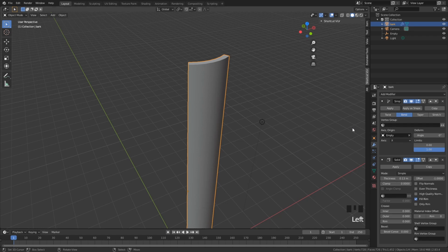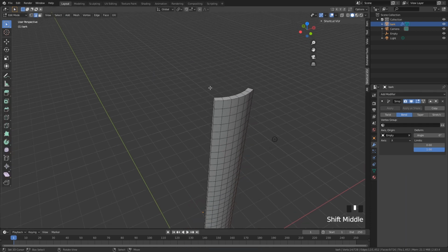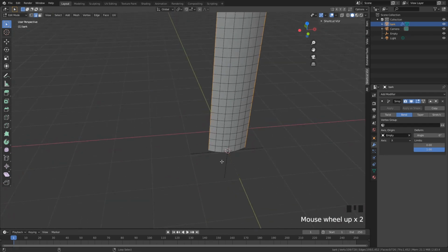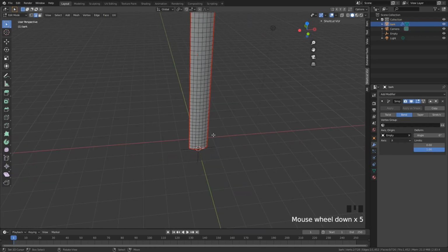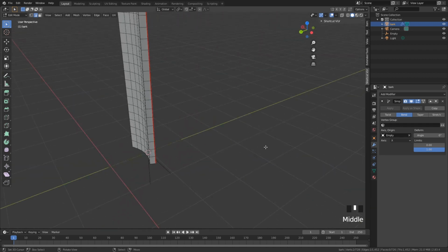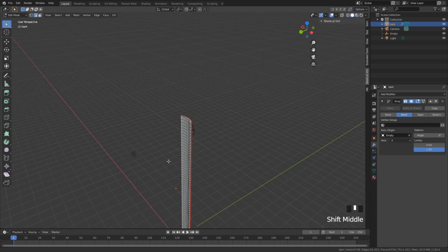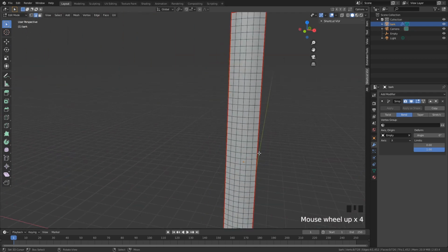What I want to do here is I want multiple of these. Before I'm actually going to duplicate these, I will apply the solidify modifier and then UV unwrap this model. So I'm going to select this and this edge loop, Ctrl E, mark seam, because this part is going to be the most important one, and then just every single one of these edges as well. So these, and the fourth one will be down here. Ctrl E, mark seam. Very, very easy.